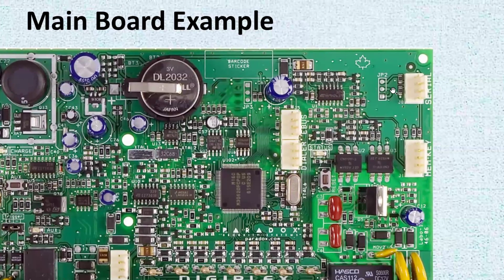But what else you can do is buy something called an Ethernet interface or IP interface. It looks like about this size. See, this is a watch battery here, about that size, a box. On one side, it plugs into the serial interface here, the serial port, and on the other side, that box has an Ethernet jack, so you can plug this into the network. In this case, all you have to do is plug your computer or laptop into the network and establish a connection with this security alarm through the network. And the monitoring would not be done through the phone line, it's going to go through the network system.